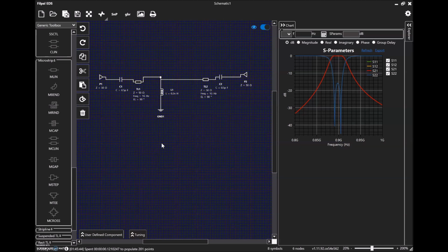In the last video, we showed you how to construct the single mode resonator using the ideal transmission line, and we also played a trick to achieve a dual mode resonator response by simply adding a shunt inductor at the midpoint without additional length added to the transmission lines, which means the overall size was not changed, and we were able to achieve a dual mode resonance as shown in this graph here.